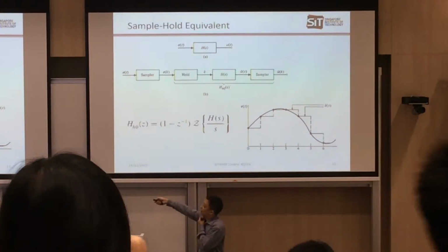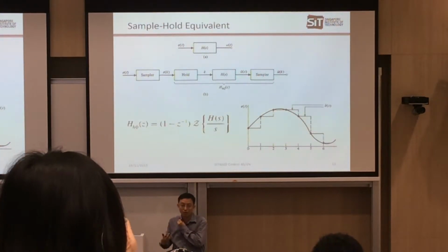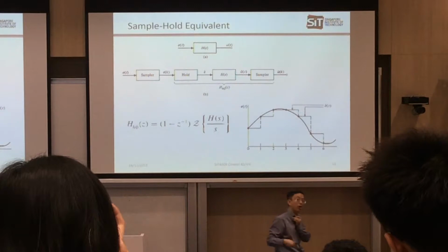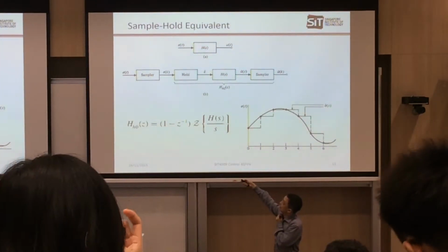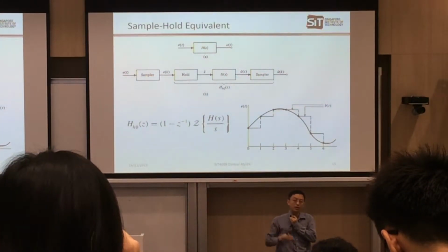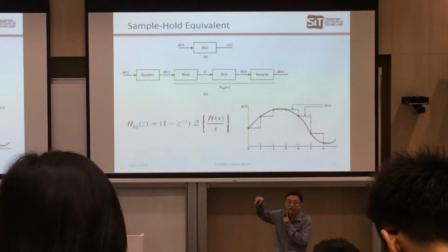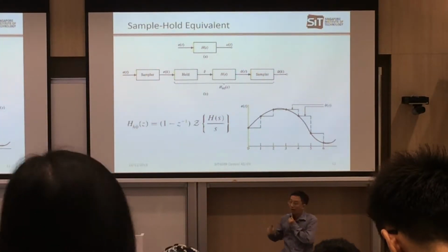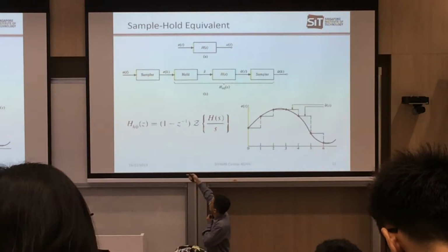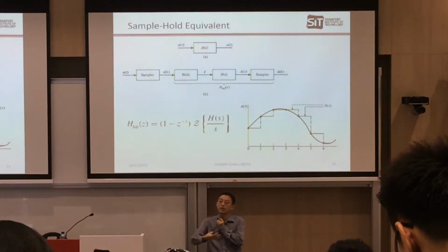So if you have your input, the sensor will measure your input, then you compute the error, right? So basically the error data e(t) is your input to your control block. From the physical world, the velocity, the voltage, the current, all these things are continuous data, right? So you have your e with a small e, which means your data is continuous. After you obtain the continuous data about the movement, the voltage, the pressure, and so forth, then before you go to your computer, it will only look at the value at certain sampling times.